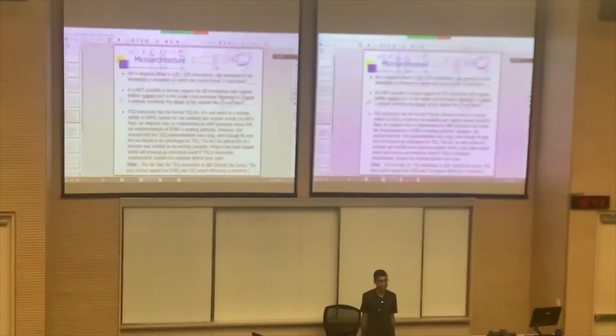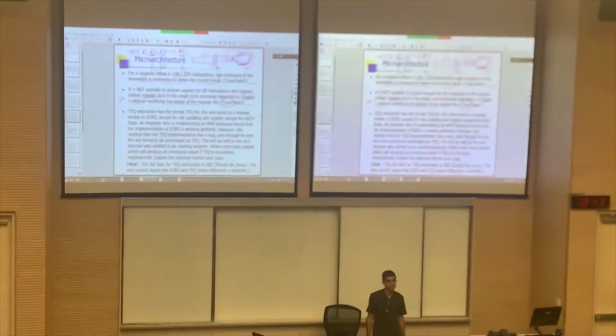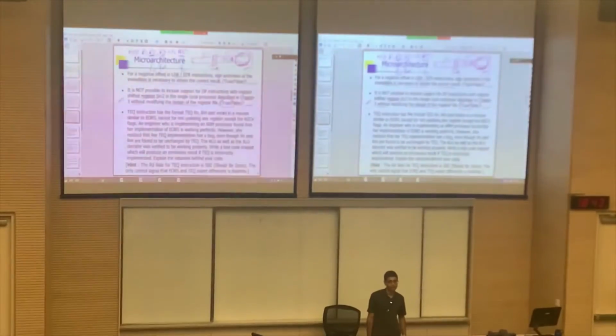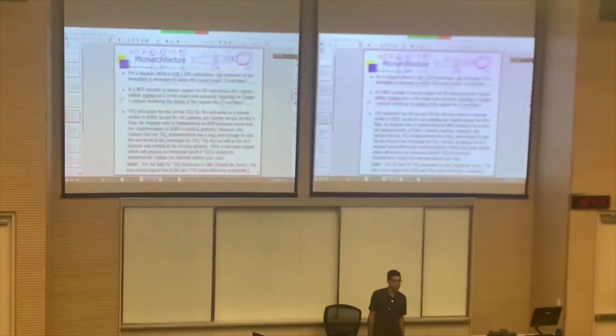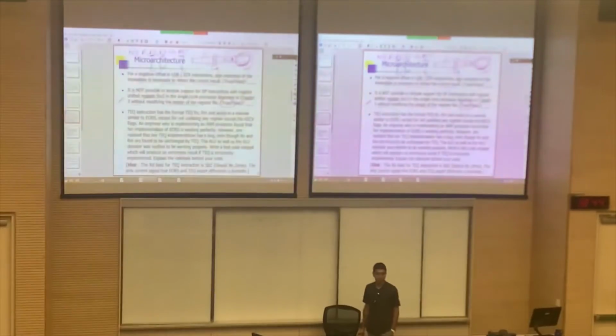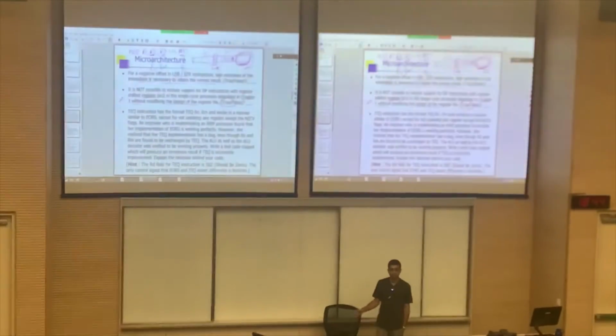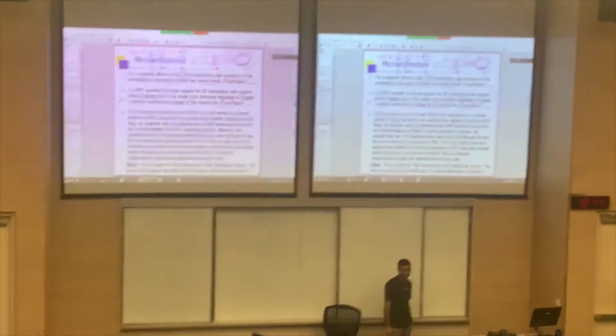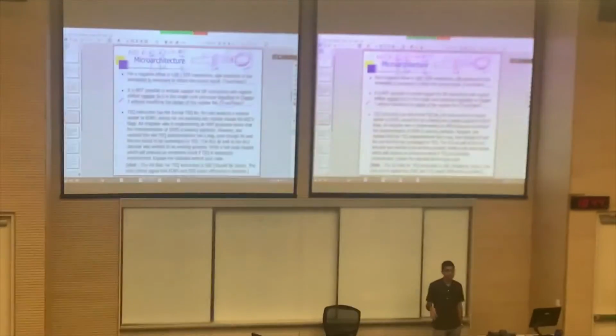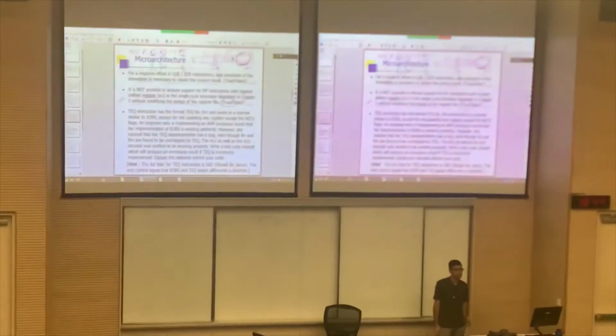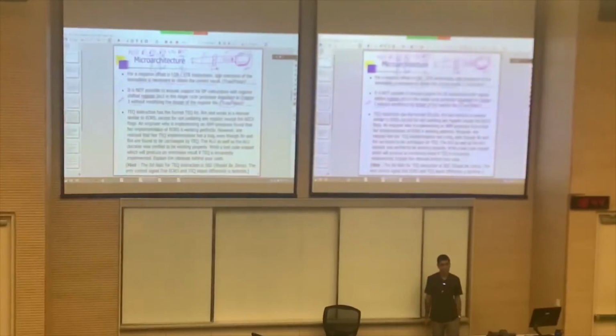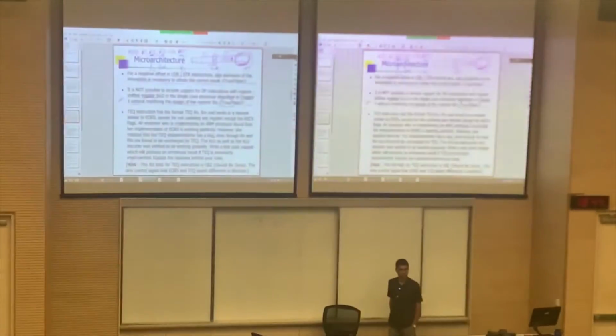Right? Because the whole instruction has to be executed in a single cycle, right? And your register file, based on your chapter 3 design, can only read 2 values. So if you read a third value, you have to modify the register file. But later on, with the wisdom that we attained in later chapters, we know that it is possible to keep the register file design as such and still have this instruction. But it won't be single cycle.